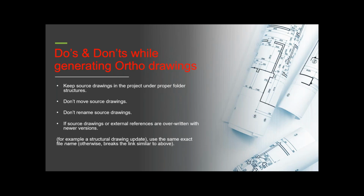But even if you need to move some folders at a later point of time in your project, do it within the project browser window. Don't do it in Windows Explorer. What happens is the association between those ortho drawings and the Plan3D model can be disturbed when you try to do that in Windows Explorer.